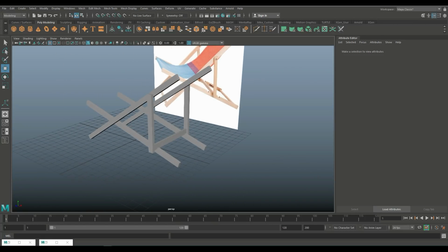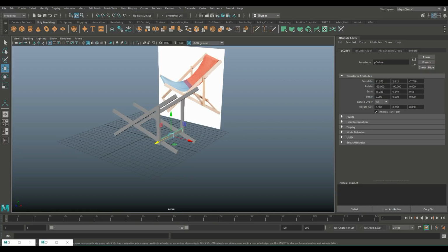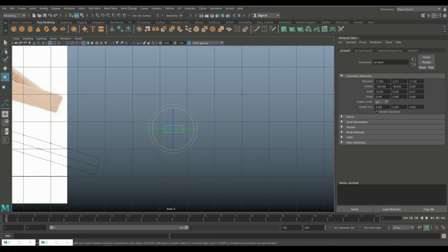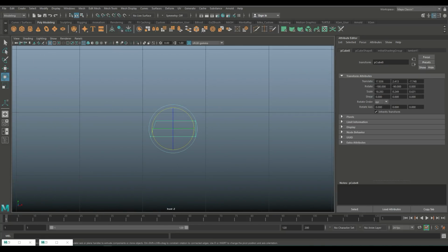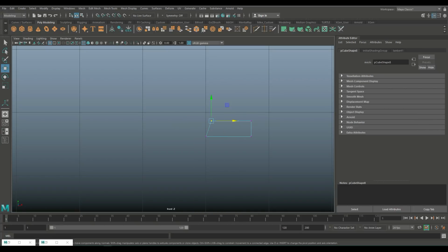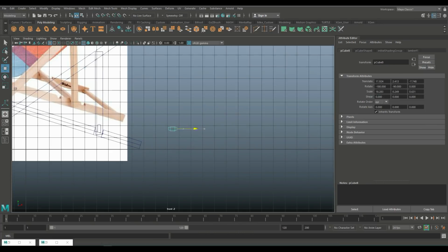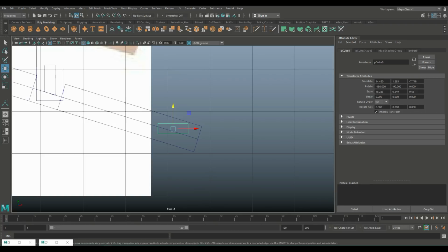So we need a little cross section at the end there. So we'll borrow this guy and hit Control D to duplicate, W to move backwards, E to rotate, hold on J and flip it like this. Then we're going to go in here and frame it. And because this guy is not straight, let's just make it straight. Take that vertex, hit W, hold on X, and there you go. So we're going to bring that in here and push it down here, after frame, pivot points in the middle.